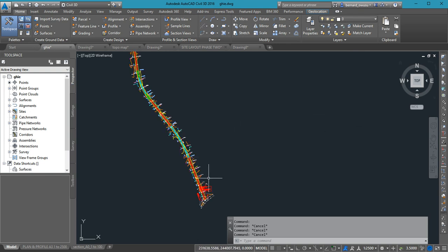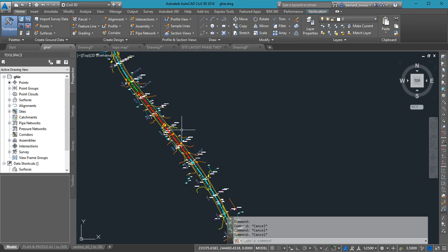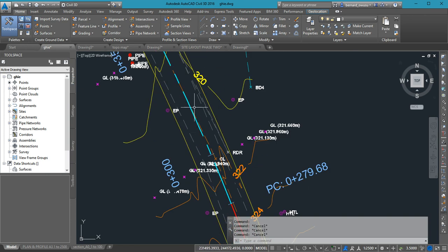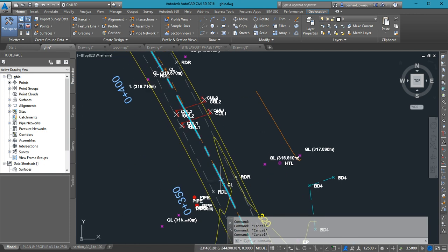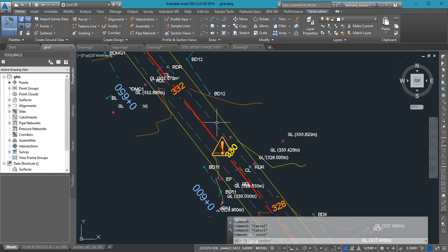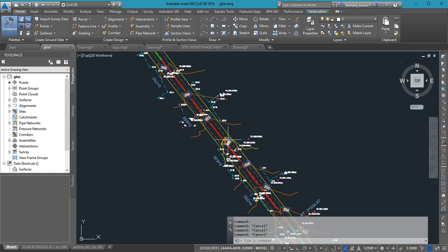Now you realize that what I've designed now is a design center line. You remember that we also included the width. Now this is just to guide us because of lack of time. If you look at somewhere here, you can do some editing, move the center line in such a way that you minimize the property impact. So you can zoom in and see whether your center line, in terms of the boundary, is affecting properties. So even before you get to the point of inserting the corridor, you know what will happen.